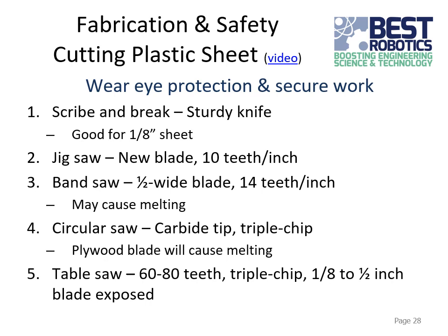Just go slow with it. The recommended blade is 10 teeth per inch, but you can see the blades will sometimes say if they're good for cutting plastic. Again, make sure that your workpiece is really well supported, otherwise the jigsaw may break pieces off.